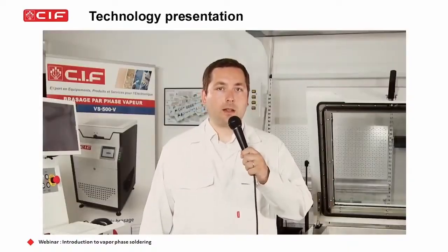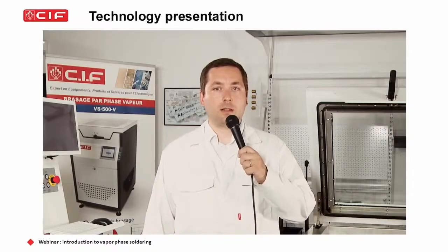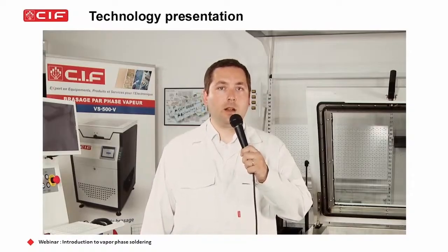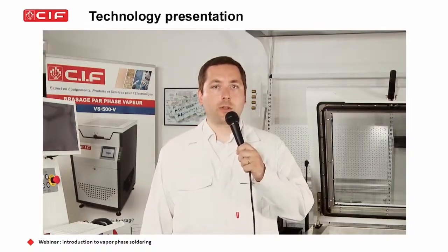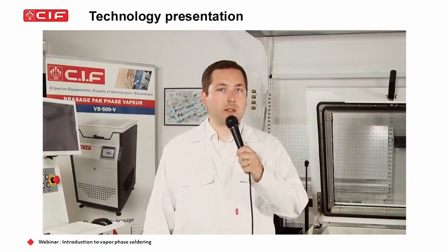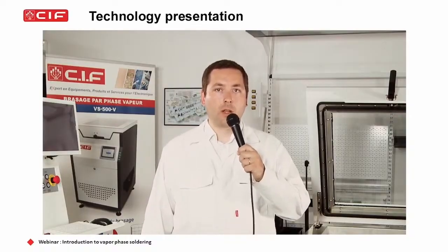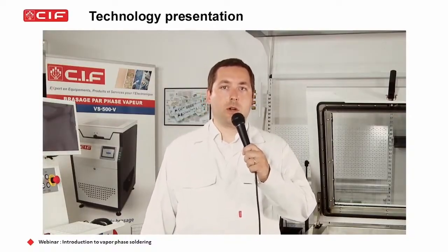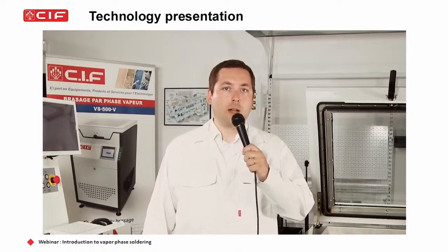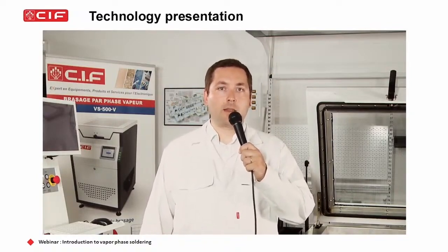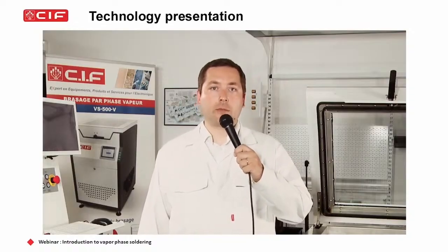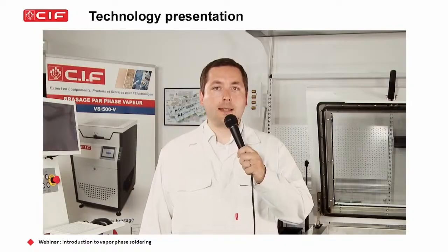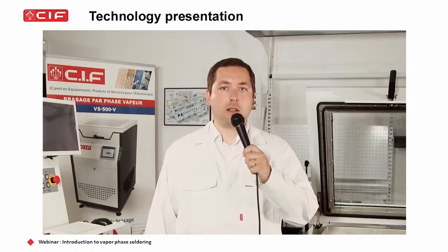The third very interesting advantage is regarding inerting. It means removing the oxygen during the process to avoid any oxidation of the solder joints. This is what the system does with the Galden vapor that will replace the air and therefore the oxygen. This provides a longer lifespan of the solder joints, and it is also linked to the next advantage, which is the void reduction.